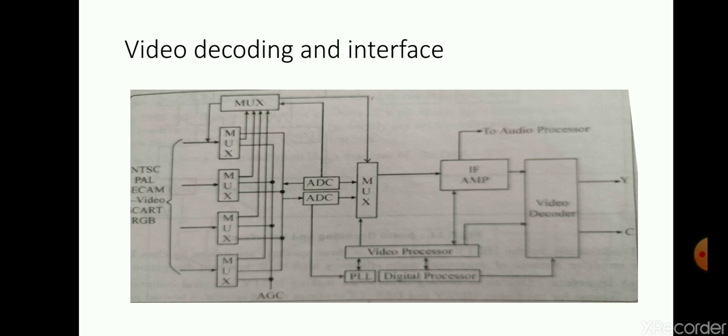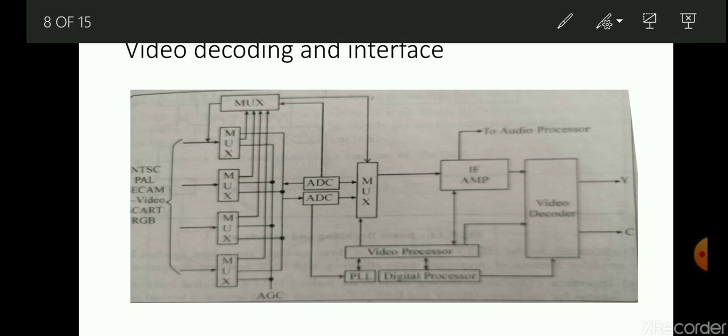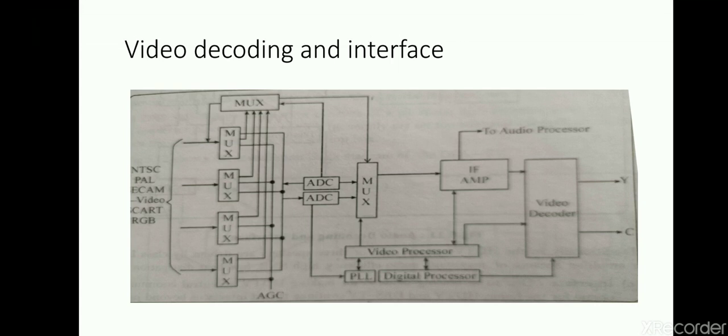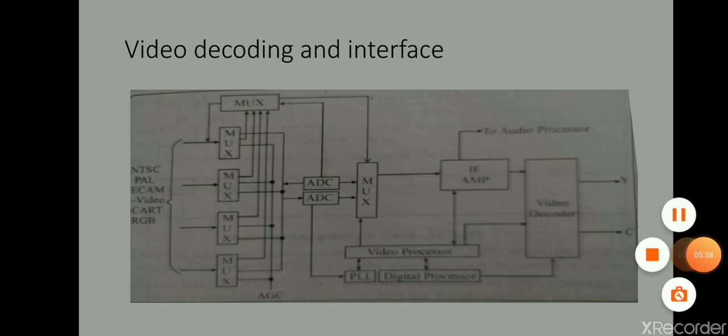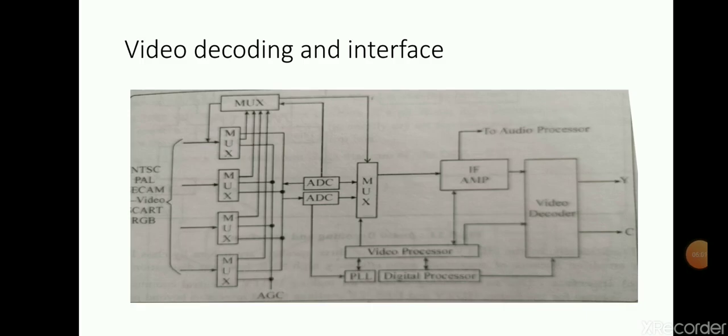In case of video decoding and interface, the HDTV supports high resolution with 3D adaptive filtering. It supports SD systems, NTSC, PAL, SECAM, S-Video, etc. Hence, it is important to select video decoders, analog to digital converters, and video buffers that allow a mix of performance capabilities, so that the performance of the system and cost will be tuned.